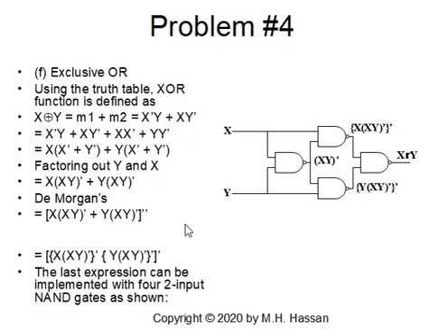Exclusive OR gate: from the truth table of the exclusive OR, it is equal to m1 plus m2, which is x'y or xy'. We can expand on this by adding 0. We can add as much 0 as we like, so we add xx' and yy'. We factor out x and we factor out y, so we'll get this equation.